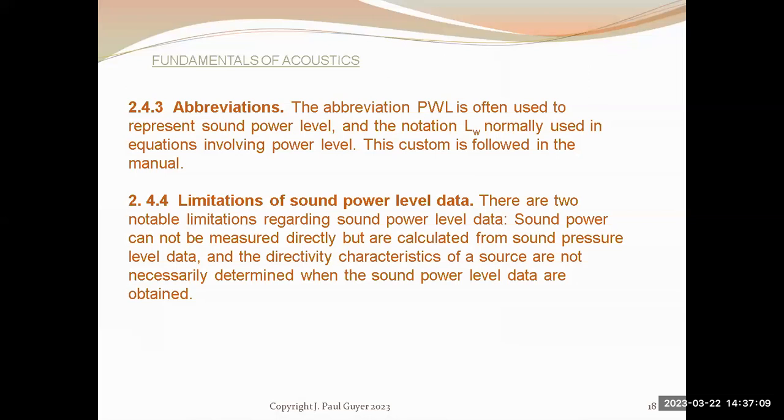The sound is being propagated outwards, and the only way you could measure in the field the sound power being produced by a source is if you could measure all of those sound vectors and add them up and get the total sound power being produced. But it's not practicable to do that. Nobody's invented a sound power meter that could do that, and there's really no need for that characteristic.